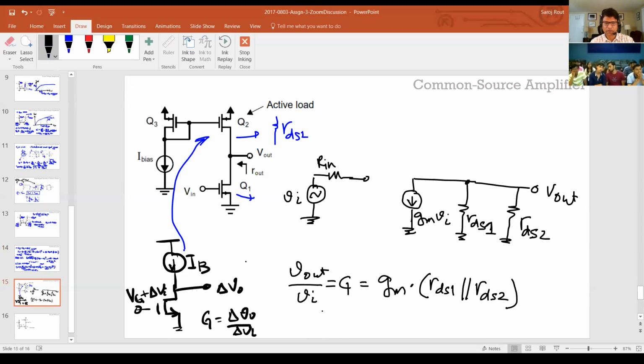I'm not going to go into the problem right now because I think it's pretty straightforward, but do you have any questions for this problem? So essentially, if you want to get a certain gain, you just follow the method. If you're given a current, you have to find the GM. You can size the W over L, or given voltage, you size the W over L to get the current. It's basically the same process.